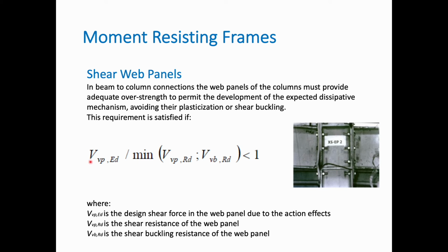So the design force in the web panel, due to the action effects, over the minimum of the shear resistance of the web panel or the shear buckling resistance of the web panel, should be smaller than 1.